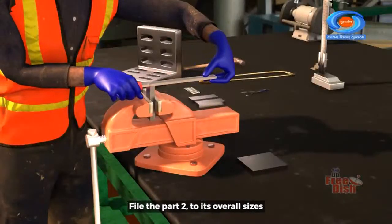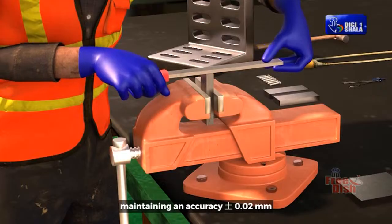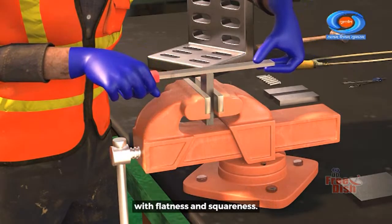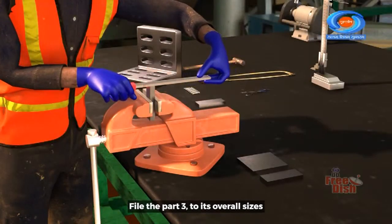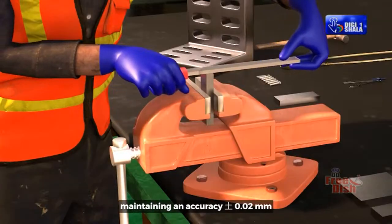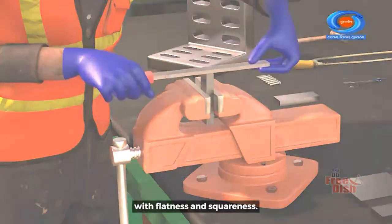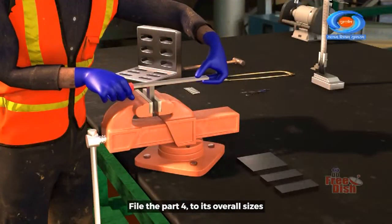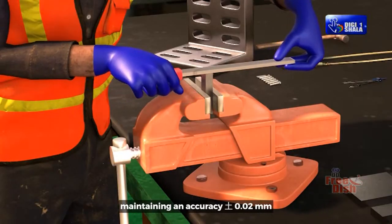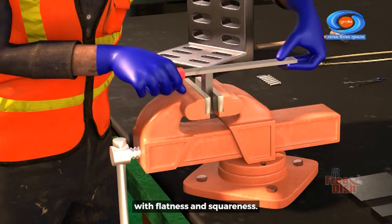File part 2 to its overall sizes, maintaining an accuracy plus or minus 0.02 mm with flatness and squareness. File part 3 to its overall sizes, maintaining an accuracy plus or minus 0.02 mm with flatness and squareness. File part 4 to its overall sizes, maintaining an accuracy plus or minus 0.02 mm with flatness and squareness.